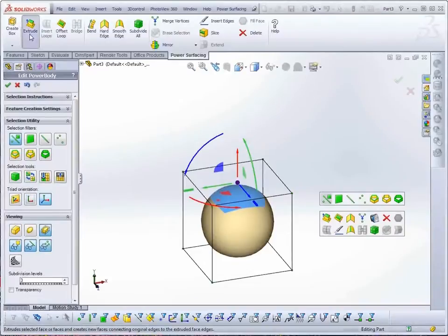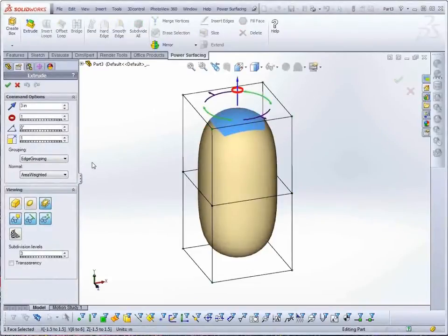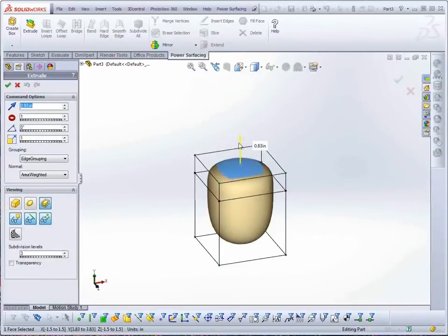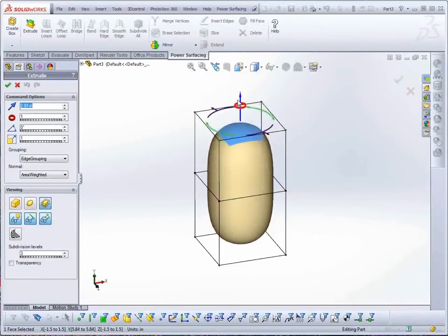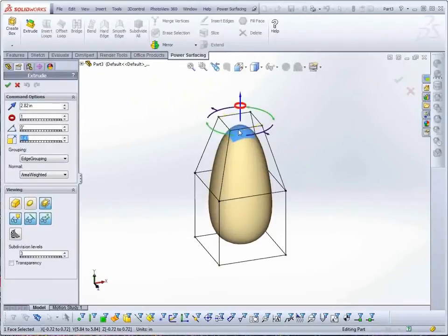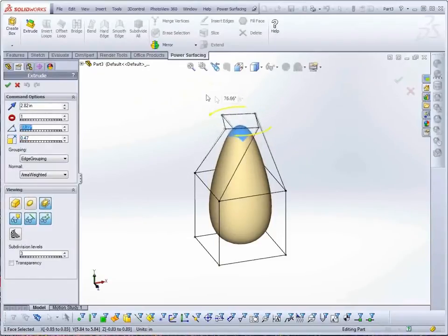The face is extruded out, and the extrude parameters are shown in the Command Options rollout over in the Command panel. You will also notice that the context-sensitive gizmo has changed to reflect the new options. With Extrude, you can adjust the extrude distance with the Distance gizmo, scale the extruded face with the purple Expand gizmo, and rotate the face with the green Rotation Angle gizmo.